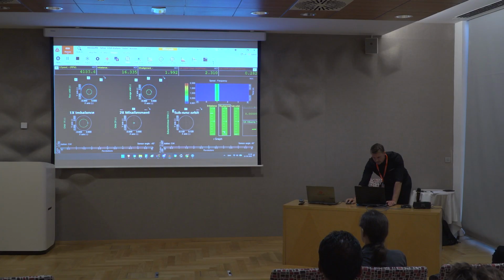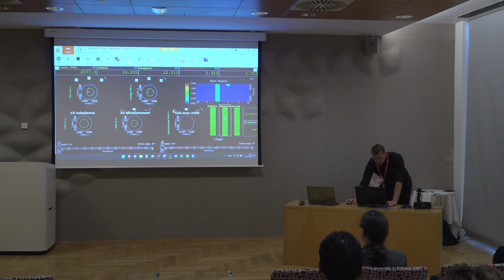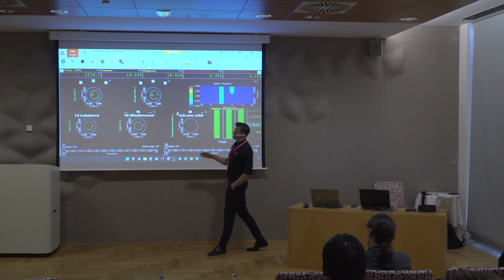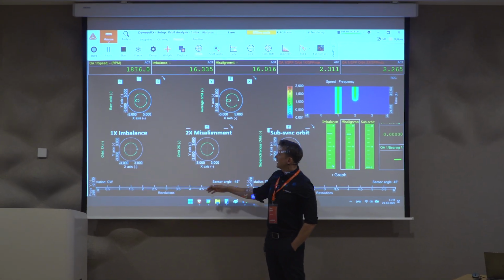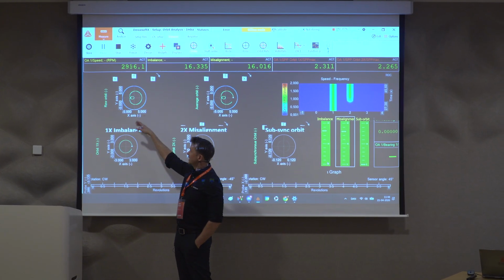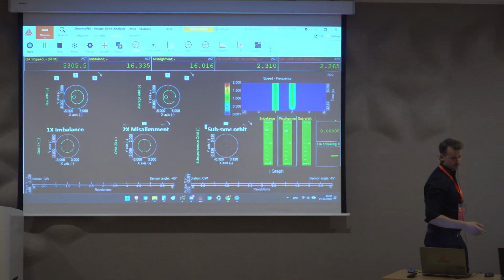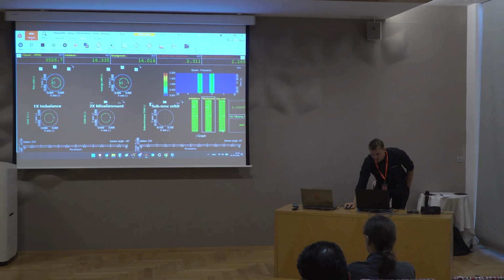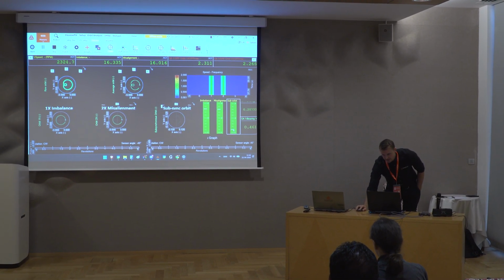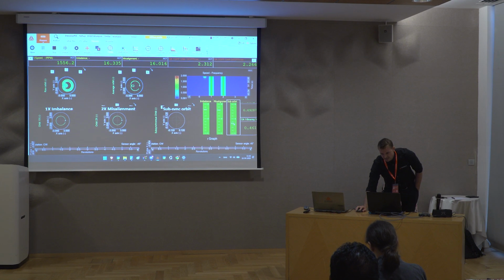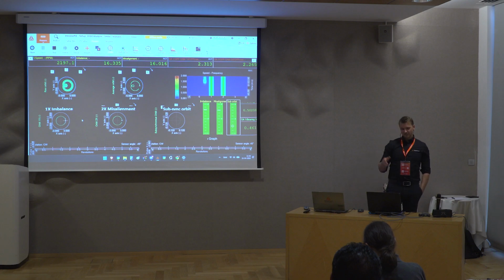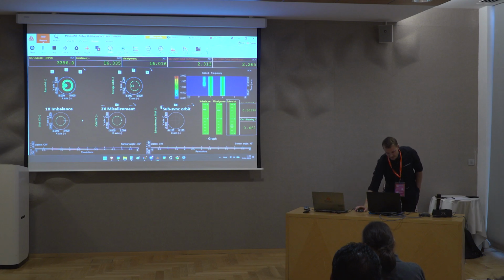If we then also add a second order component to it, we can see that now we will also, on the filtered one, have the amplitude shown here, and the raw orbit containing everything will have a shape like this. And then we can also add a subsynchronous component to it, which is something that happens less than 1 time per revolution. Then it begins to have some movement in one revolution and some other movement in another revolution, and that's why it looks a little like this.